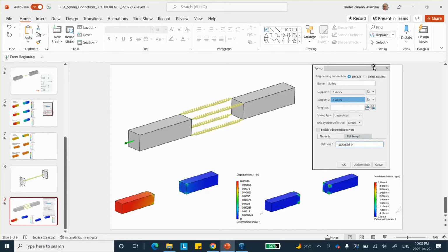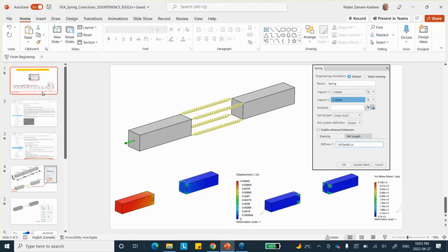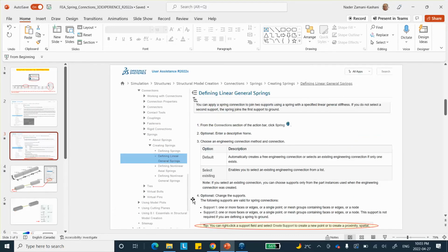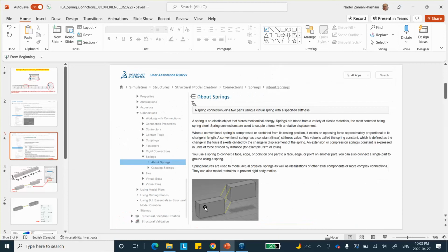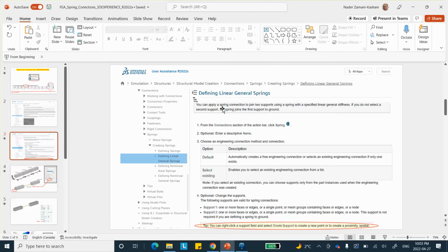By the way, notice that when you do these point to point, vertex to vertex ones, you don't get that option of kinematic and continuum or structure anymore. But if it's point to anything else, you'll get those options. And the description of the coupling type, you may have to look at the documentation, but it has to do with how the averaging is done.